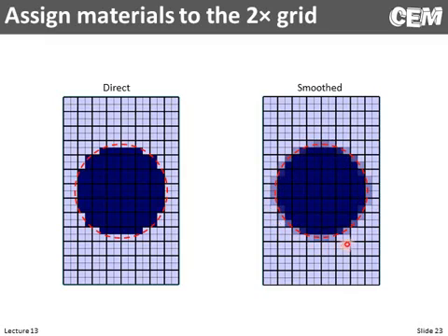This is actually better. This leads to faster convergence, meaning we can get away with larger grid cells, faster simulation for the same amount of accuracy. So this is simpler to build, but will require a bit higher grid resolution. This is a bit more complicated to build, but we can get away with coarser grid resolution.